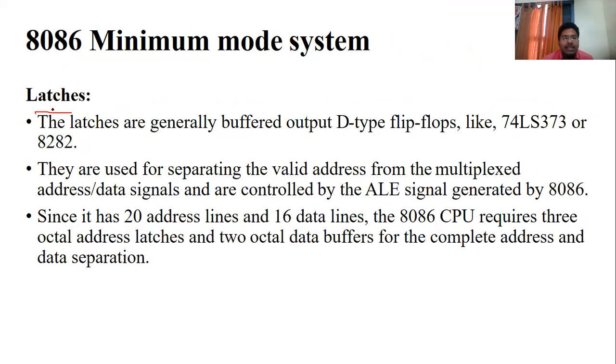So what is a latch? A latch is nothing but a D-type flip-flop. Why are we using these latches? You know that we have the address lines AD0 to AD15. Then what are the other lines? A16/S3 to A19/S6. We are going to convert address lines to data buses, or address to status.